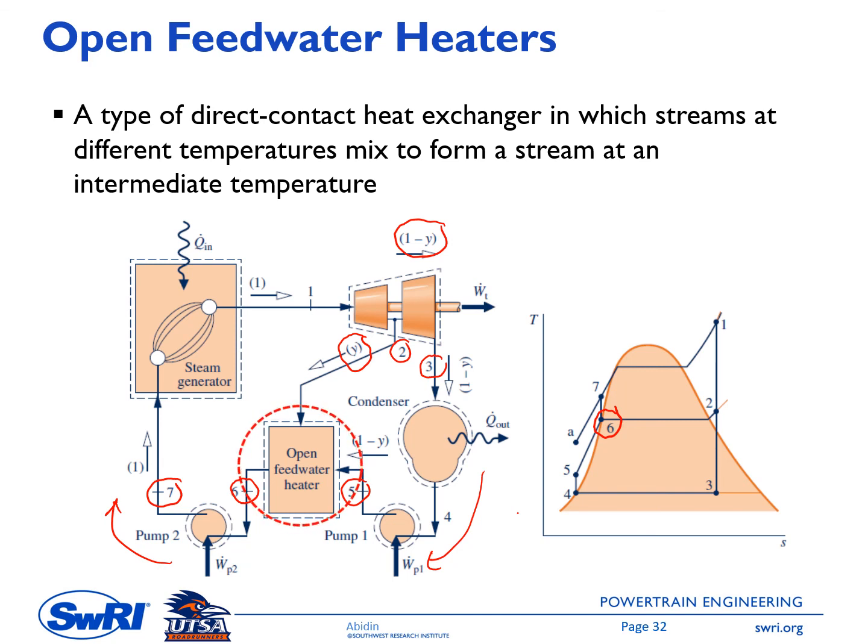And then if you compare with the previous modified Rankine cycle, you can see that on the second stage of the turbine, the mass flow is reduced because some of the mass flow needs to flow to this open feed water heater. So there will be a reduction of this turbine power. In a regenerative Rankine cycle, the operating condition is in such a way that the reduced fuel energy more than offsets the reduced turbine power, and therefore the system efficiency increases.